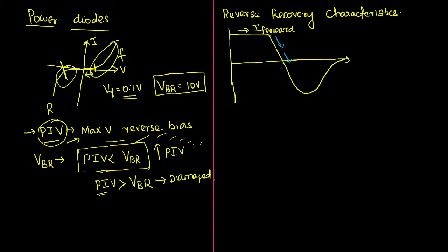So the first term here, let me break this reverse bias region into two. See here, the diode is almost crossing the 0 point. Yes, after that we will start getting negative characteristics. So basically when you try to switch off the device, you will have two zones, right? Here we are not going up to the last zone, we are going up to 25% of the maximum reverse current, divided by 4. 1 by 4 means 0.25.